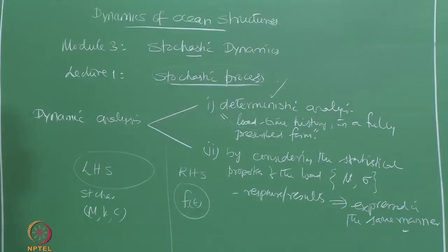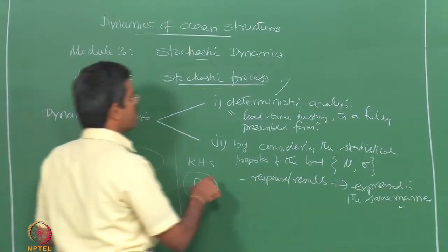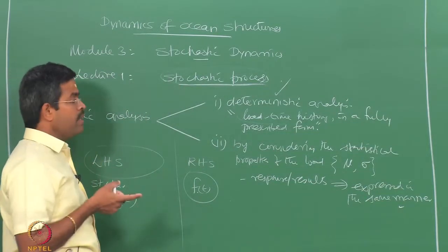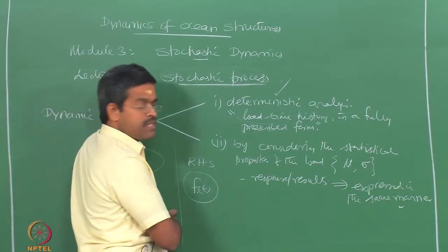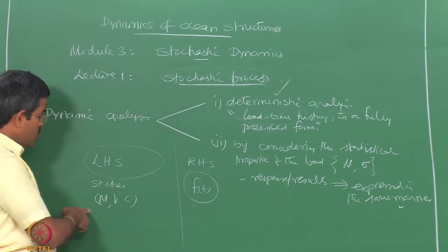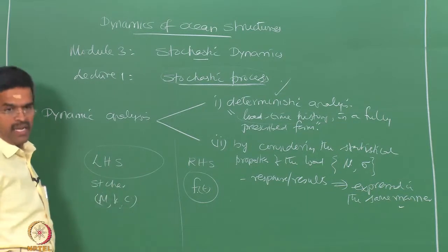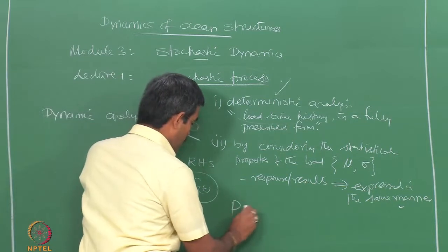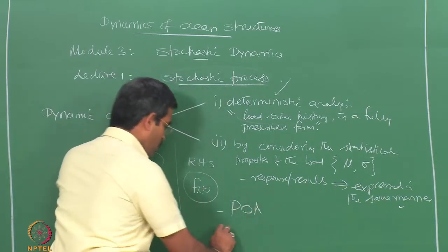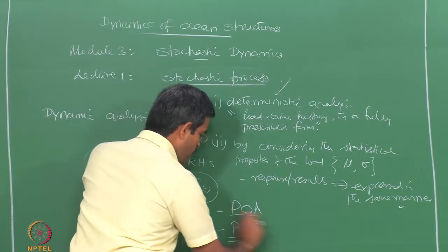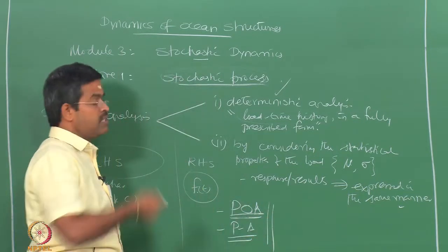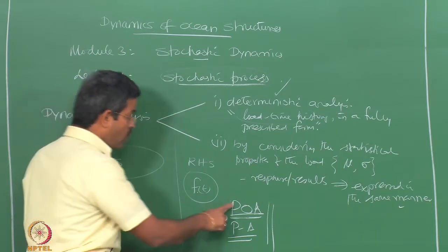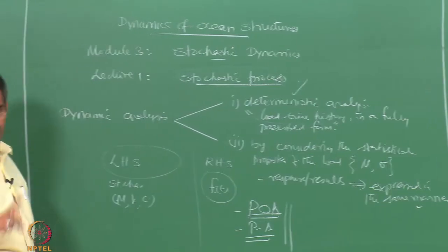Okay. So, if you look at the whole scheme of explaining the method of analysis in dynamic scenario, it is governed only by the load. It is generally not governed by the system. Okay. It is true in dynamic as well as static analysis, and it is also true for higher order analysis like non-linear. For example, pushover analysis, for example P delta effect. All these, if you see the classification of analysis in general in structural generic algorithms, are derived only based on the loading criteria. It is never based on the form or the geometry of the structure at all.